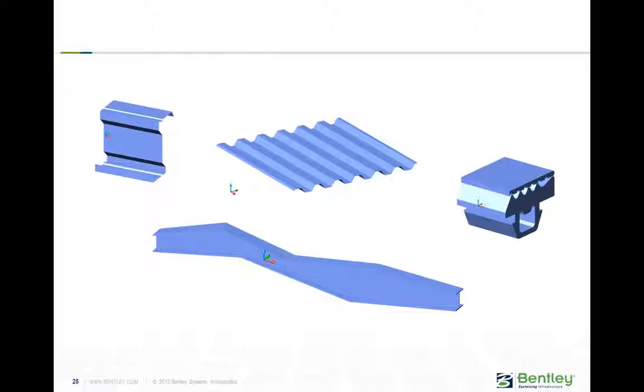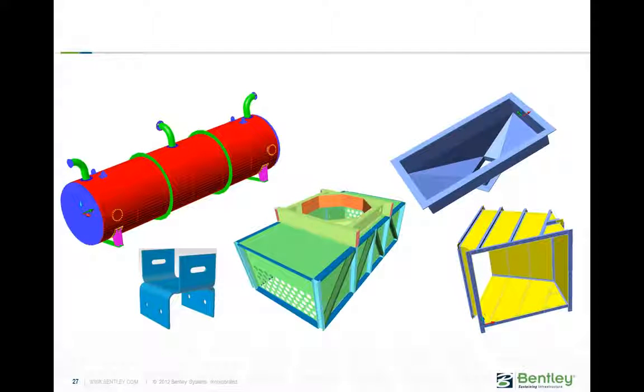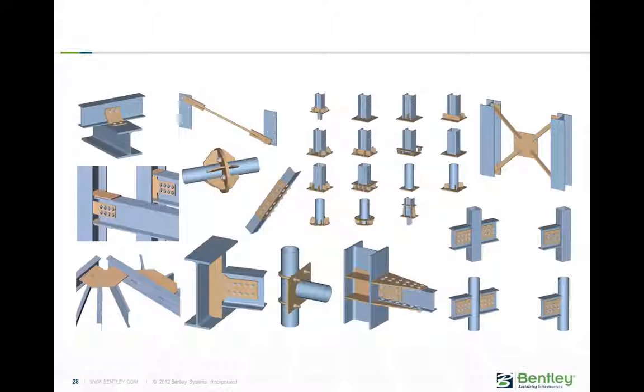The idea of ProStructures is to create a complete 3D model and create all desired 2D documents out of it. We provide not only open databases for standard shapes. Anything that you can define by a closed line can be an object in ProStructures, and it is almost as easy to create them. This includes plate work, including bending and unfolding of plates.